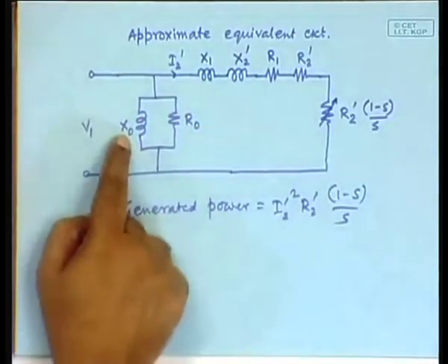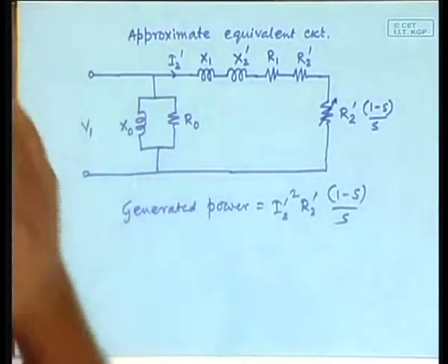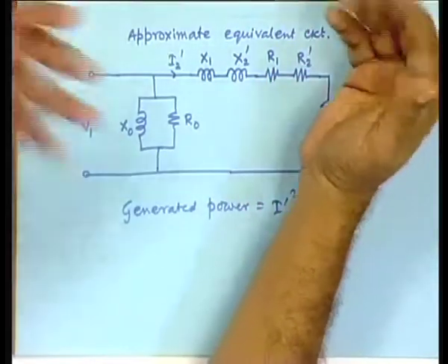Well, how is the reactive power generated? Where is the reactive power generated? In a power system, active power we understand. The whole power plants are there for that. There is a turbine that rotates the generator and gives the active power to the supply. All right, that is fine. Where does the reactive power come from? Reactive power is generated by capacitances and consumed by inductances. So here is an inductance that consumes the reactive power, and so the grid has to have some capacitance in order to generate that reactive power.